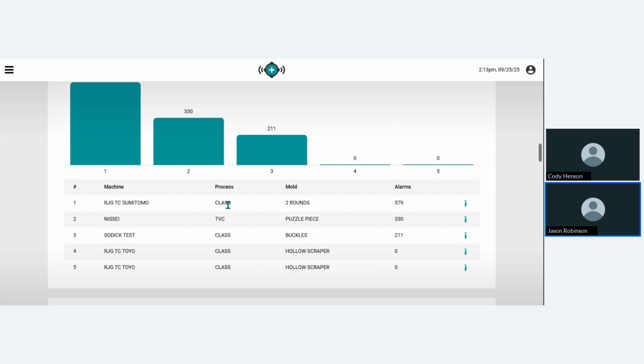So you may have a single mold that runs maybe different colors of material. So the alarm values are slightly different based off the color concentrate, or maybe not the best thing to do, but sometimes people run a mold with totally different materials. So you have different settings, different alarms, different templates. All that lives under the process. Okay. Maybe different cavity inserts is another example.